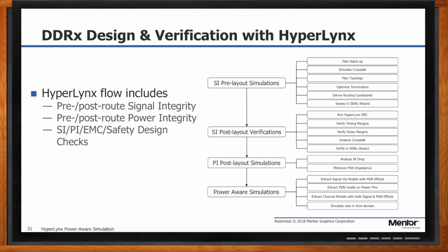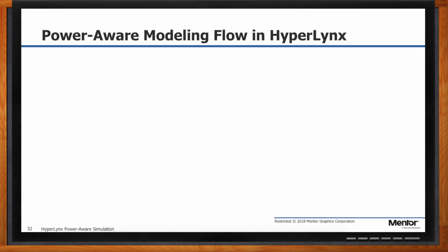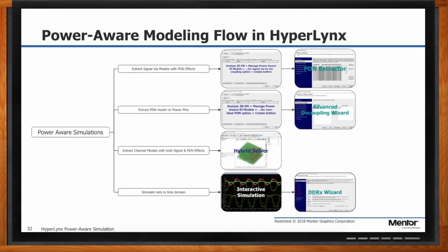When we look at how we model those interactions, because that becomes the key point, right? We talked about these three different interactions between signals and the PDN. How do we actually model those things? Well, we have to have a PDN model. We have to know how we're delivering power to the supply pins on the chips and what those frequency characteristics are. We have to have a model of the signal-to-signal coupling through the power cavity. And then sometimes what we actually do is we create a grander model that has everything in one piece. But what we do is first we run these 3D electromagnetic simulations to create these coupling models, and then we bring those coupling models into our simulation netlist and then run a simulation to show us how they affect design margin. Now, one of the interesting things that happens here is that even here, there are different trade-offs.